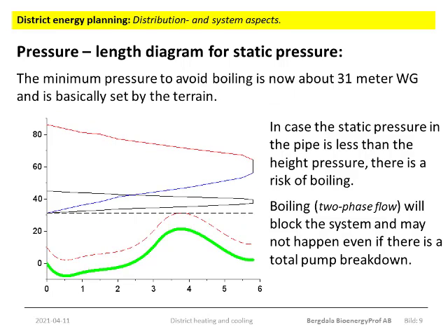And that is what I have done here. You will observe that I added an extra 10 meters as a margin. At a distribution temperature of 110 degrees, a boiling limit of 10 meters water gauge corresponds to a temperature margin of about 15 degrees Celsius. So the distance between the thick green line and the dashed line is a safety measure, equivalent to approximately 15 degrees temperature increase in the district heating water.